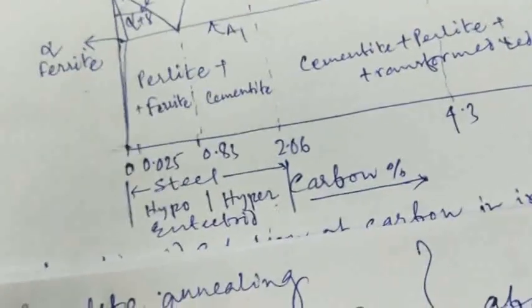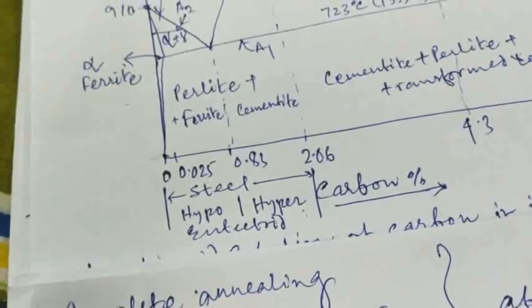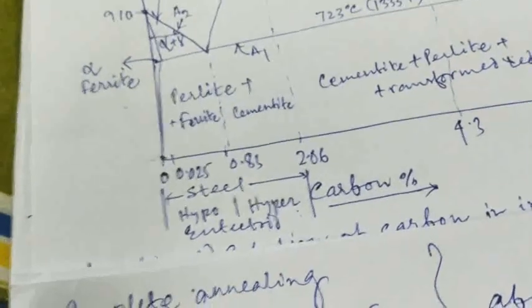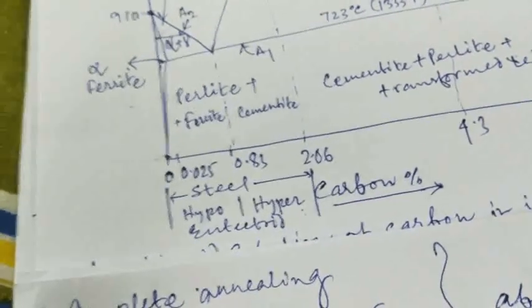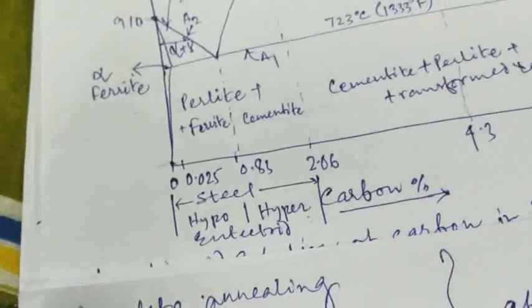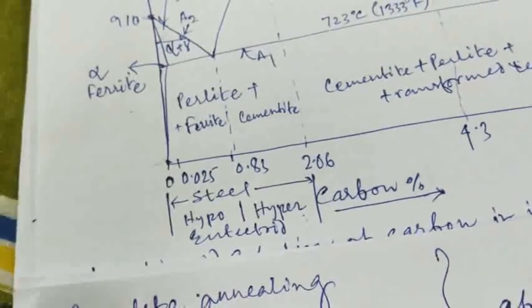After rolling and forging of hypereutectoid steel and air cooling, the structure is pearlite and reticular cementite. This kind of structure is hard and brittle, not only difficult to cut but also easy to deform and crack in the later quenching process.